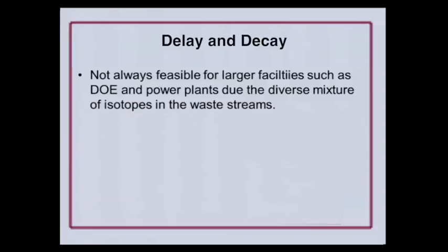It's not always feasible for the larger facilities like DOE and power plants because of the diversity of the mixture of isotopes that we deal with. You have anything from isotopes with a millisecond half-life up to isotopes with several years half-life, all in the same waste stream. So it really doesn't make sense that you would set it aside, let it delay off, or decay off.